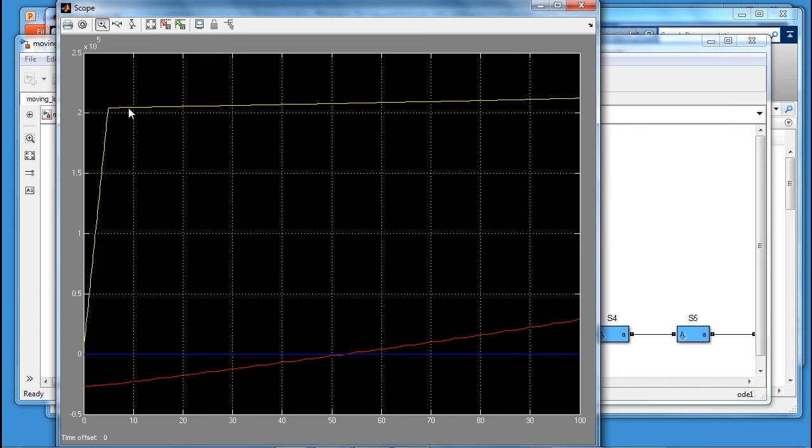So as the load's moving along the line, there's more resistance, so it needs more power to feed the constant power load as it moves, which is the ramp we're seeing here. And I've also put in some rather large inductance values, so we can see that the reactive power requirements are changing quite significantly as well during that period. And I'm doing this only for visual purposes.